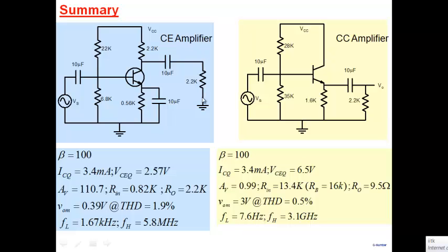So this is the whole of all the amplifiers, all these circuits that you find. Most of them are a combination of these 3 stages: a common emitter stage in some form, a common base stage, or a common collector stage. The transistors are being used either in this, or in this, or in the common base. So these are like the 3 primary colors. And you should recognize what each one of these 3 primary stages' characteristics are. What do they give us? Common emitter is here, common collector is over here, typical characteristics that you see here. Common base we have seen earlier. Okay?